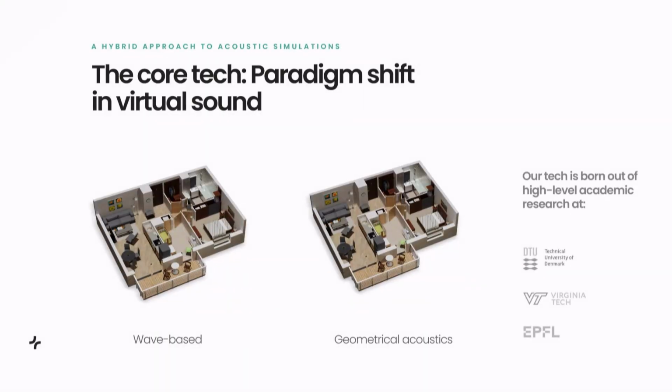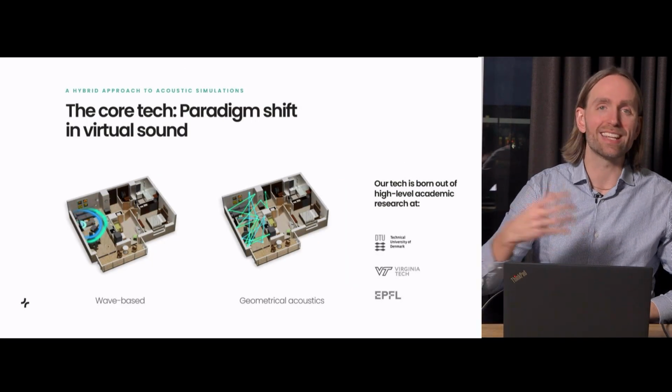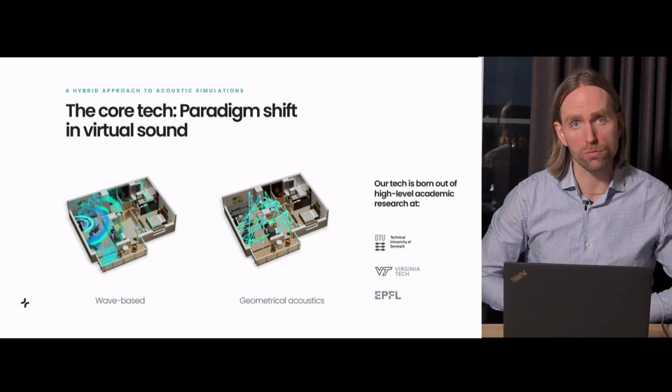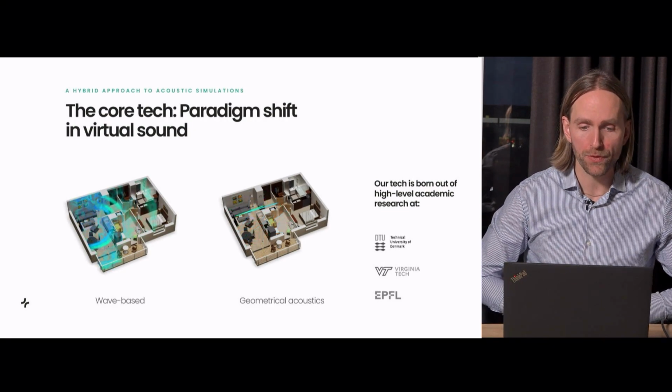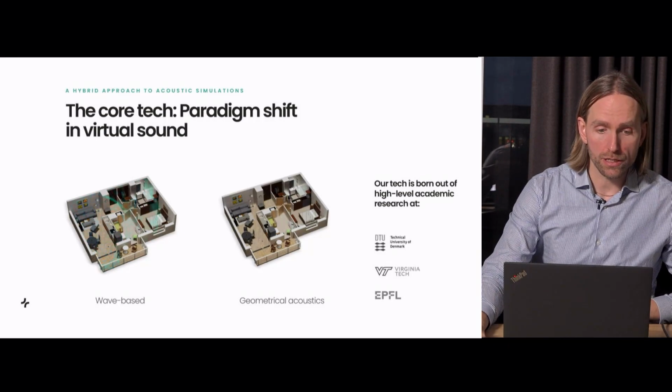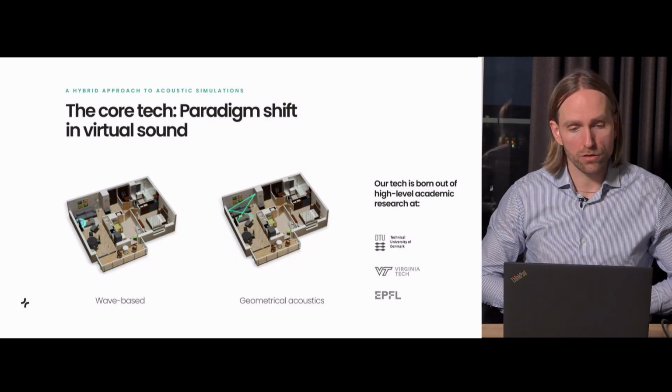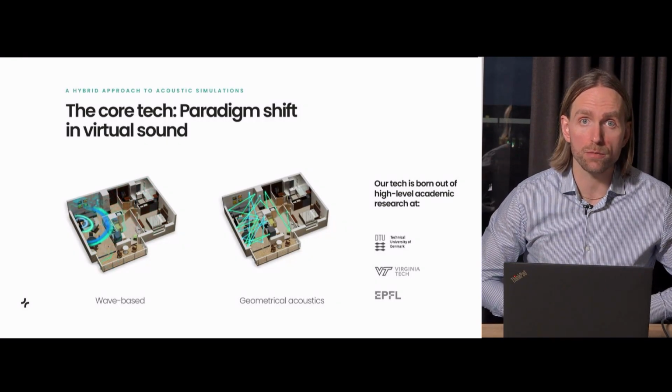So our core sound simulation engine comprises two algorithms or two methods for simulating acoustics. For high-frequency modeling, we use what's called geometrical acoustics, which has been the industry standard approach for doing room acoustic simulations for quite some time. Whereas for low frequencies, or low to mid frequencies, we offer wave-based simulations.